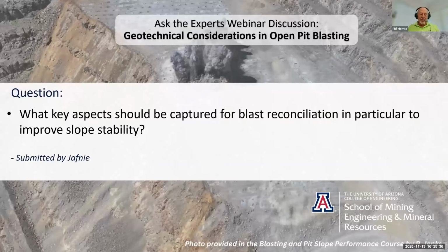If you don't control crest loss in your blasts, then you won't achieve your slope design criteria, and you'll end up with flatter slopes. So rule number one is control of the crest loss and achieving the design criteria.